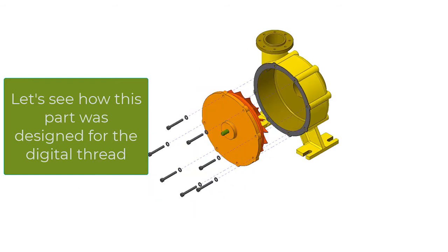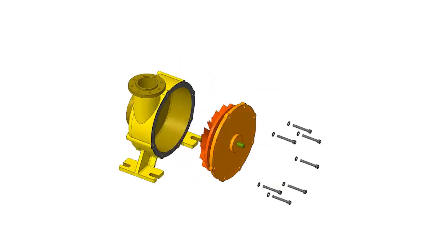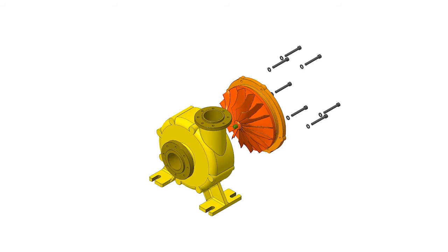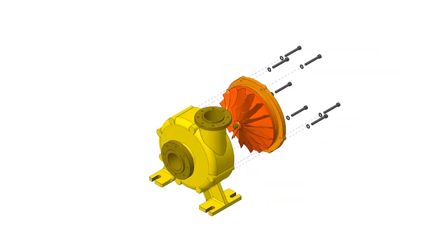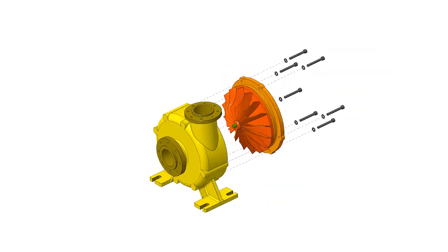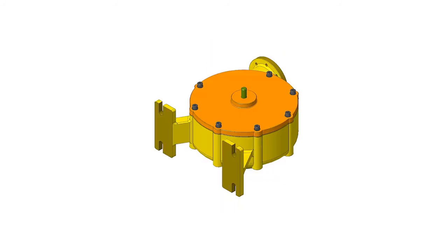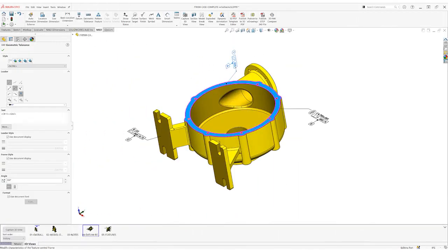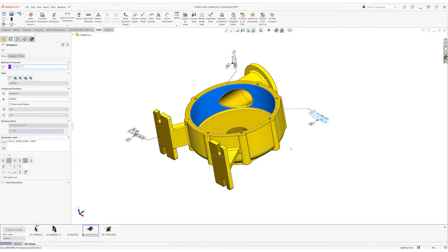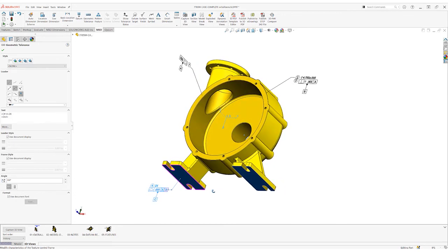It is, of course, true that we do not just build parts, but really we build assemblies. So here is how the pump case fits together with its mating parts. And notice that we've specifically chosen the datum reference frame for the pump case using the context of the full assembly. So the cover mounts to the pump case via datum feature A, and the impeller spins inside the pump case on datum feature B, and then the entire assembly is mounted on the surfaces that are qualified by a profile tolerance of datum feature C.